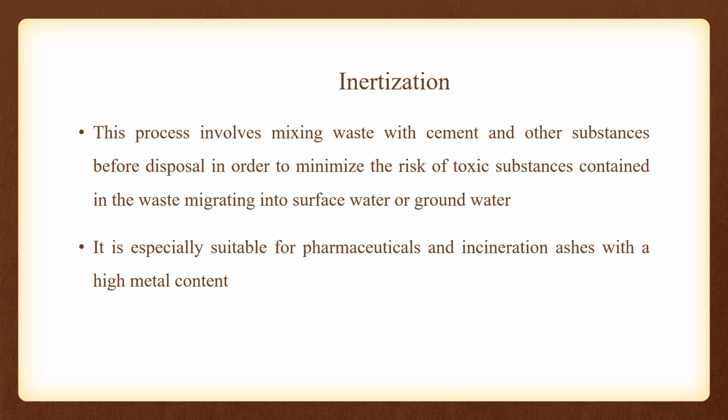The last is inertization. It is a 2 marks question also. It might be asked regarding healthcare waste management. This process involves mixing of waste with cement and other substances before disposal in order to minimize the risk of toxic substances contained in the waste migrating into surface water or groundwater. It is especially suitable for pharmaceuticals and for incineration ashes with a high metal content. This is a relatively inexpensive method of waste disposal, but it is not suitable for infectious waste management.